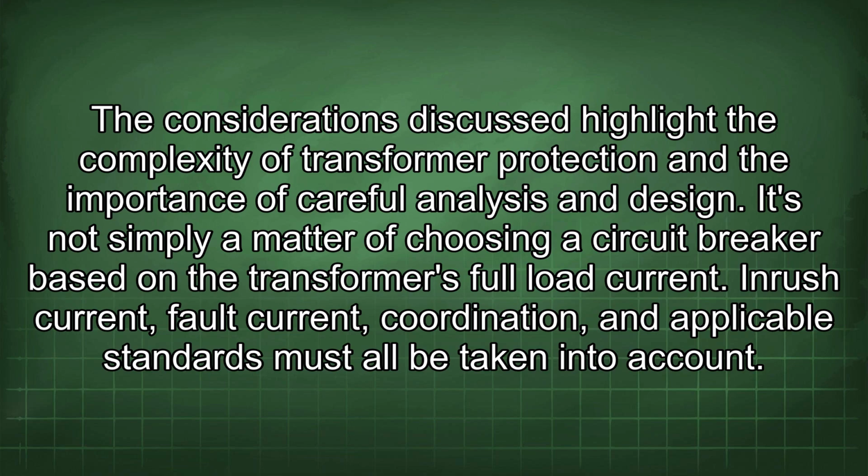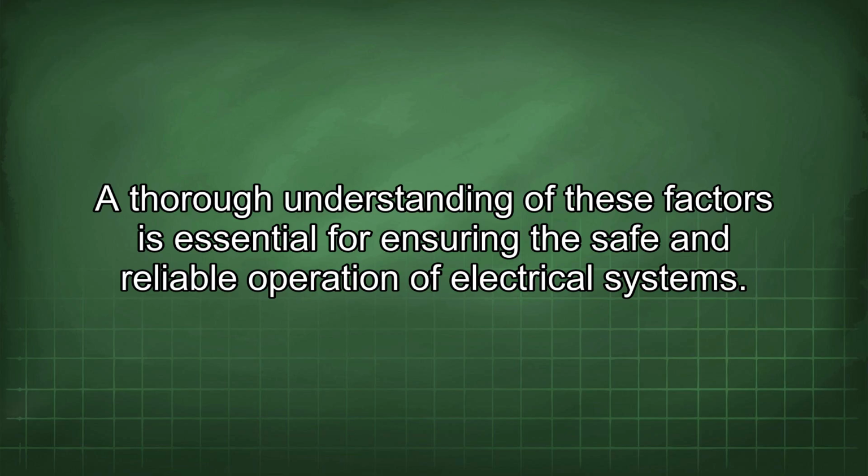The considerations discussed highlight the complexity of transformer protection and the importance of careful analysis and design. It's not simply a matter of choosing a circuit breaker based on the transformer's full load current. Inrush current, fault current coordination, and applicable standards must all be taken into account. A thorough understanding of these factors is essential for ensuring the safe and reliable operation of electrical systems.